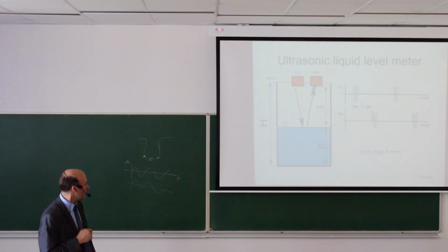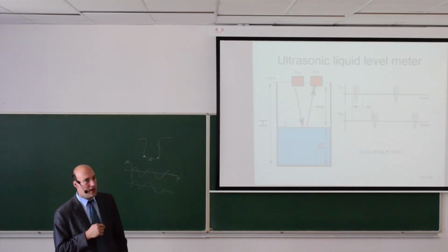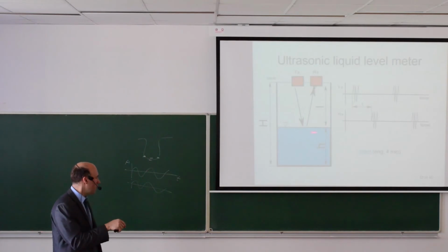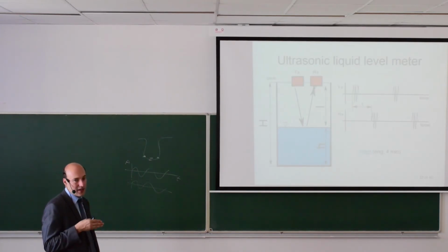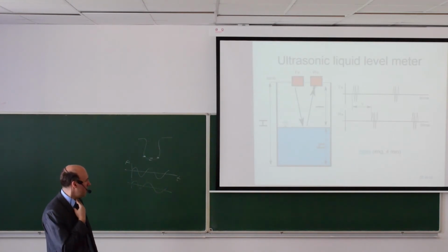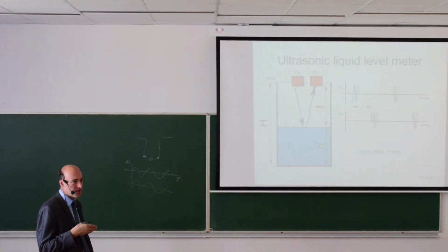The ultrasonic liquid level meter may have problems with foam. So if there is foam on top of this interface, then this foam will absorb the ultrasound, and you will not see the reflection. So applications with foams.